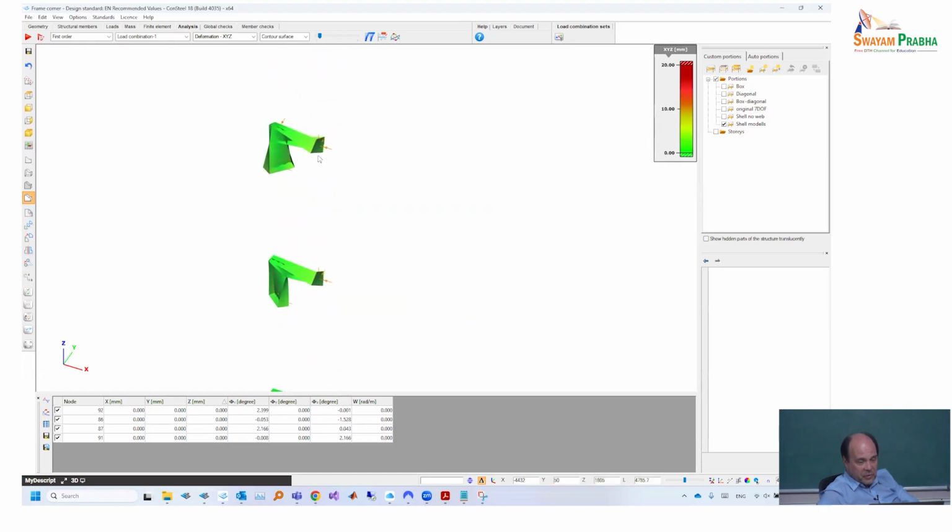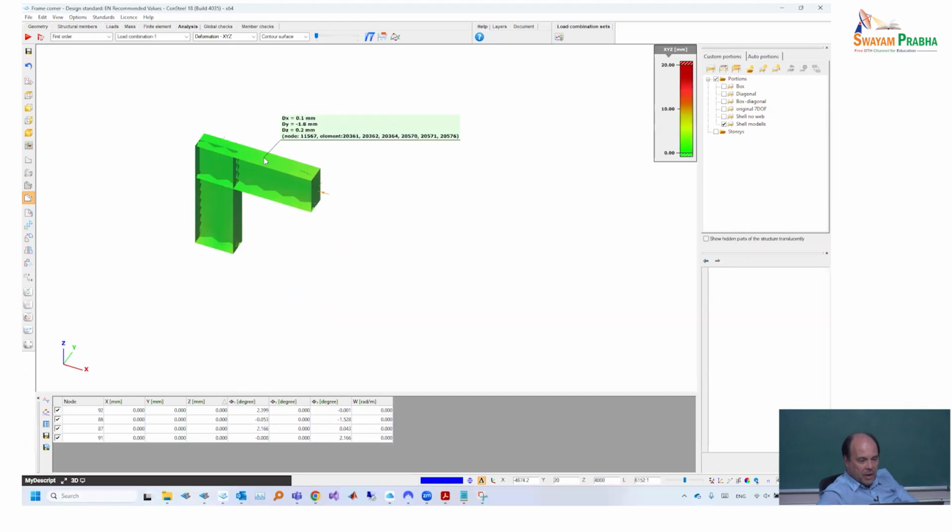And this is something very interesting because normally I think no one would expect that this happens, and you don't even see it, and probably you don't even know about this. That's clearly coming from how the warping deformations, which are just flange bendings, are not necessarily the same. So the flanges may bend in the opposite direction. That's called warping. And really the question is how that information goes from here, how we let it go, what will happen, and how we go down.